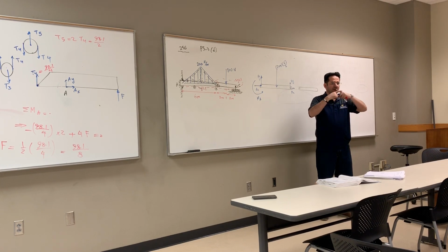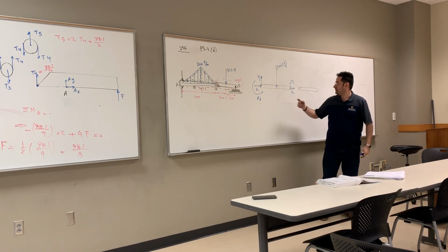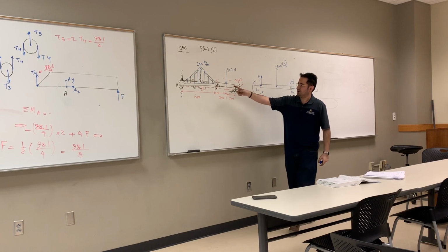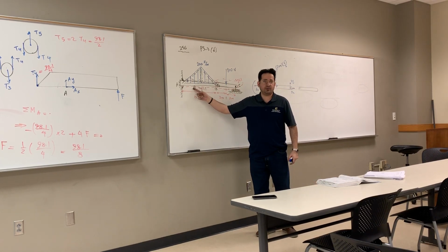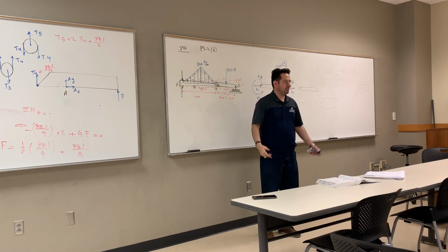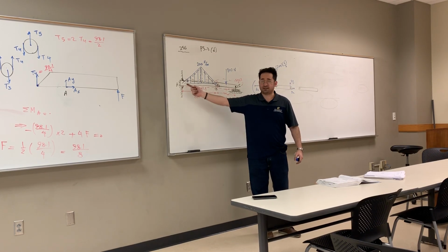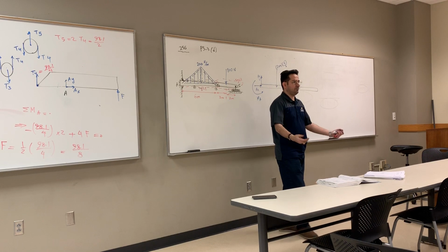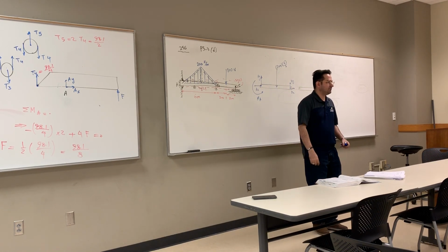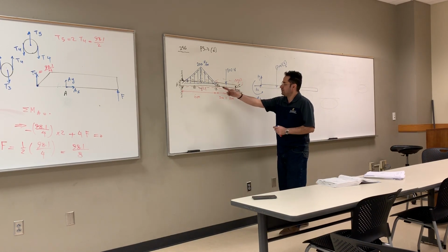Nothing is resisting me. You can easily rotate, right? So Bx, By, and continue walking, going back to the point. So I'm done with the surface force. What about body force? No body force. This is massless. Massless beam. Very light beam. That's a composite, made of composite material, right? So I'm done with this guy.